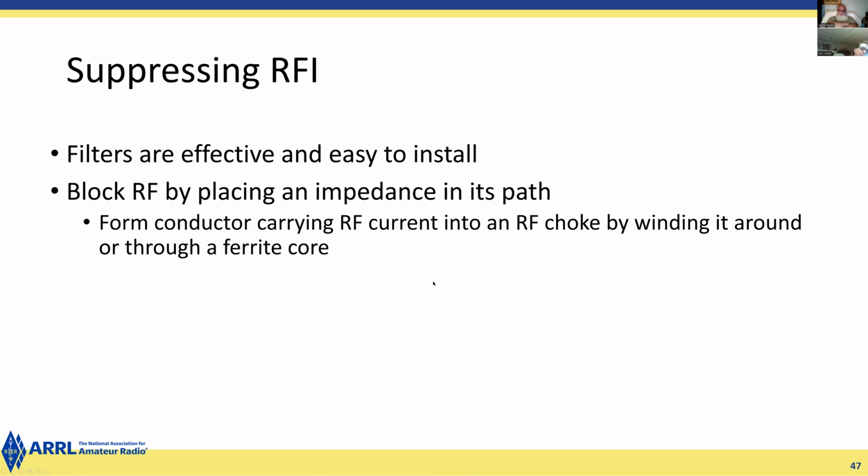How do you suppress radio frequency interference? Filters are one way. You can place an impedance in the path that's conducting the interfering signal. Now by impedance I mean resistance at radio frequencies, and next week I'll explain impedance in much more detail.